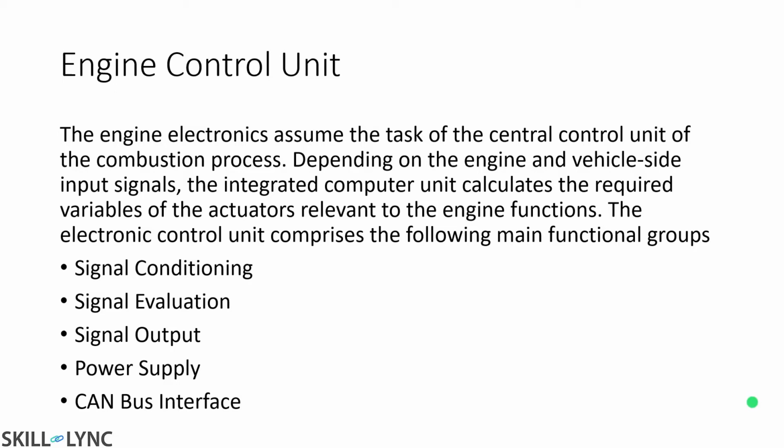A very basic example would again be the temperature control system that we took up previously. When we want to control the temperature, we're going to have to give a few inputs, so we're going to have a few sensors like the coolant temperature sensor, the oil temperature sensor, and then the air or ambient temperature, and so on. Based on all these temperatures, we're then going to understand what we have to do. There is something called a correlation, and the value of these temperatures is called a set point.